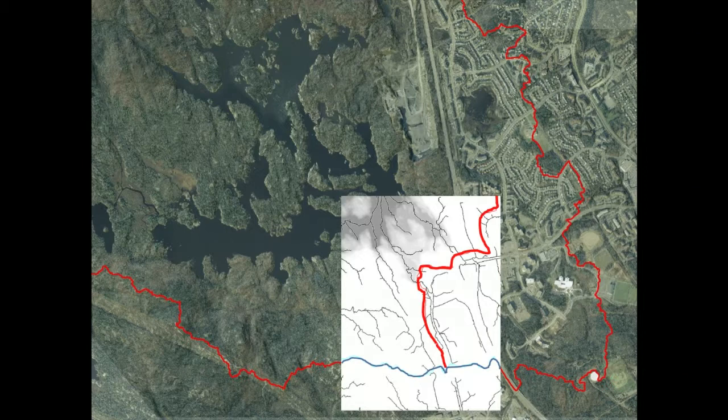This is not a specific LiDAR application because you need extra information. Beyond the LiDAR, you also need to have some map of the drainage infrastructure. But if you put those two high-resolution data sets together, you can get a much better estimation of the true watershed rather than the natural surface watershed. That's important if you're doing things like hydrological yield calculation.